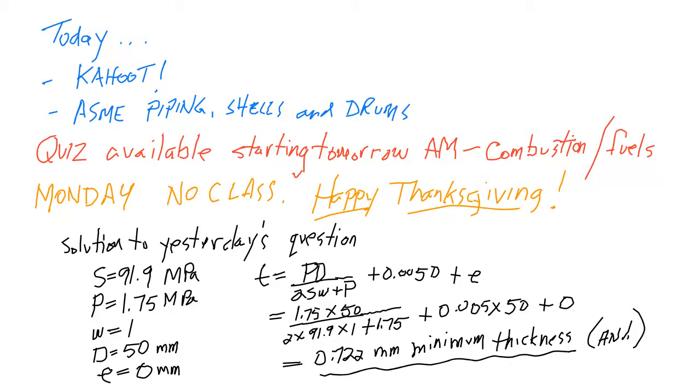Dave, this material would be okay for making what exactly? Anything outside of that? Tubes. Tubes. Okay. And if you take a look at ASME 2D, when you look up that material, SA192, the product form says tube. You can't buy SA192 plate. It doesn't exist. SA192 is, by its very definition, a tube. All right. Any other questions?